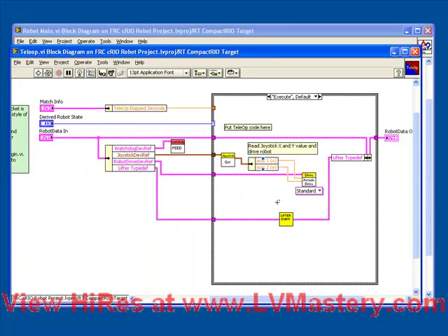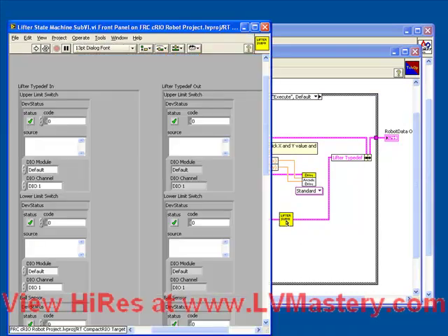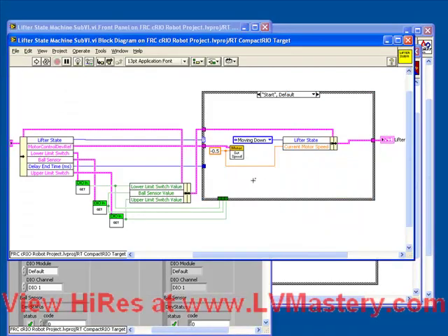This particular code we created, if you remember how it works, is a state machine which essentially automates a lifting mechanism. The mechanism moves down to the bottom and waits for a ball to come into the field of a sensor. As soon as that's read, there's a delay, after which point the lifter goes up until it hits a limit switch. When it hits the upper limit switch, it immediately comes down until it hits the lower limit switch. Then it goes back into waiting for a ball.